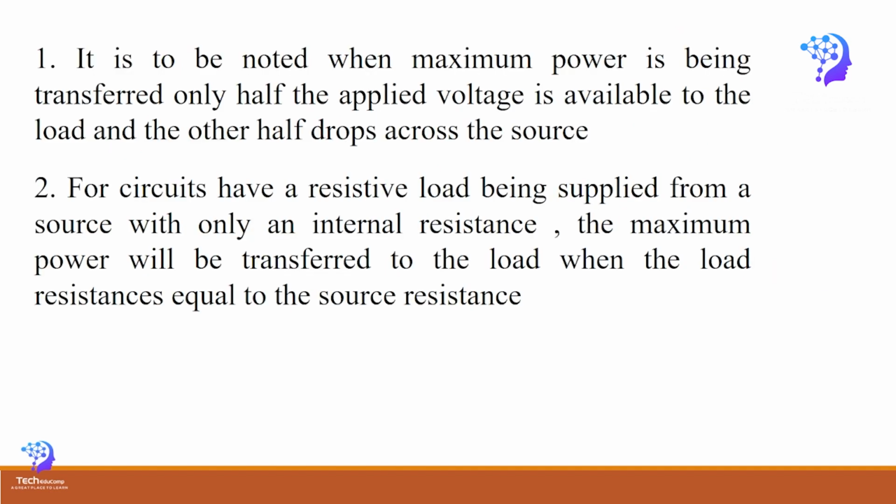To conclude today's lecture, you have to remember some points. First point is to be noted that when the maximum power is to be transferred, it only transfers half of the applied voltage to the load and the other half drops across the source. Thus the useful maximum power will be less than the theoretical value which is delivered, and will depend on the voltage required to be maintained at the load.